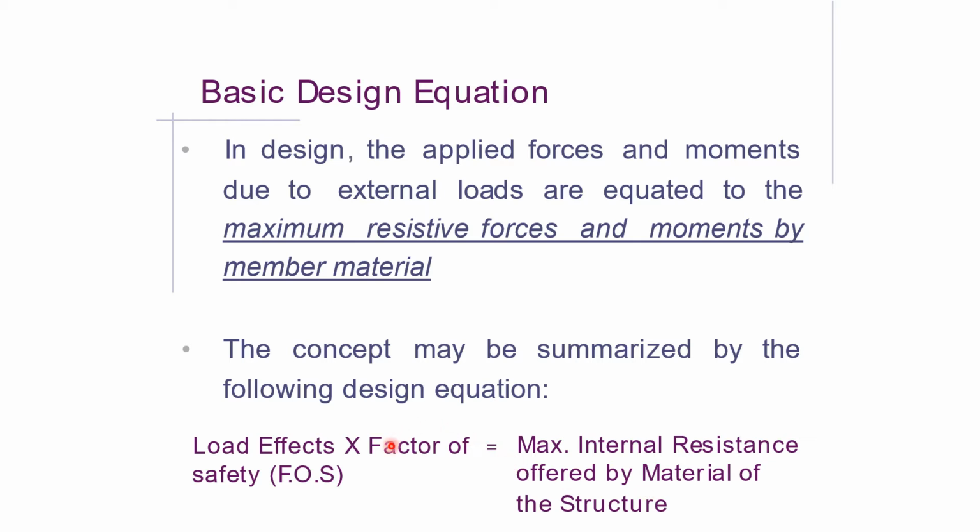Means applied loading is equated to the internal resistance or the material strength, and we enhance the load by a factor of safety. Why? To accommodate many factors like material deficiency, poor workmanship, natural disasters. So all types of things we cover with the factor of safety. So this is the basic design equation.